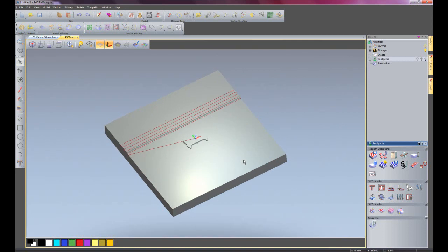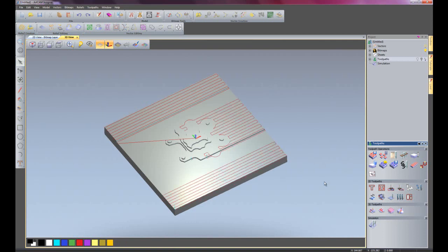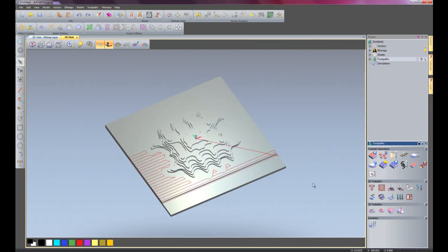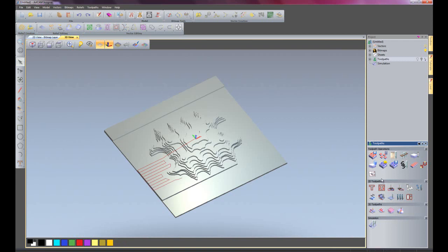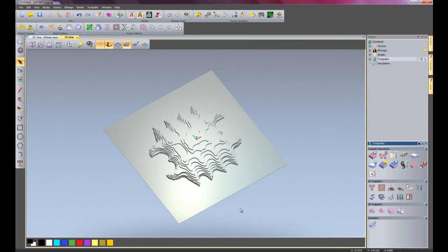Here you can see it's creating the first roughing cut, the second, and it's going down in Z slices. So there you can see it's creating our roughing toolpath. Remember, we selected to leave 0.5mm on this particular piece, so when a finishing toolpath is made for this particular part, it will just finish this. So if you have a look at the next video, which is to show you how to do a 3D raster in any orientation, then I'll show you how to finish this particular part.